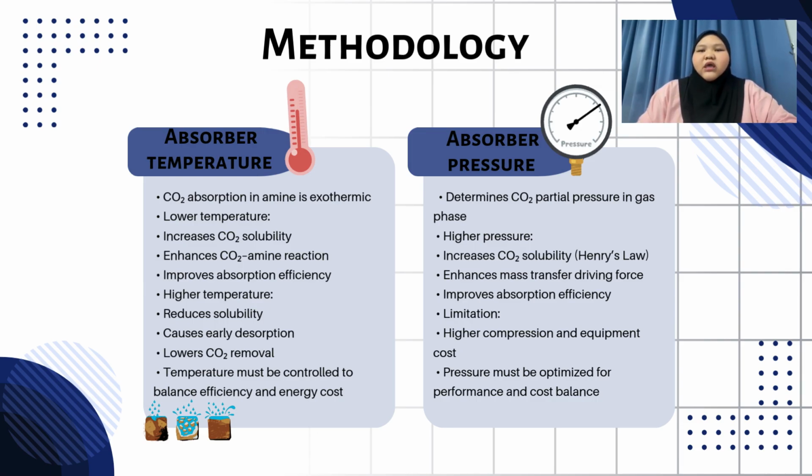However, operating at high pressure requires more energy for gas compression and stronger equipment. Therefore, absorber pressure must be optimized to ensure good CO2 absorption performance while keeping energy consumption and equipment costs reasonable.